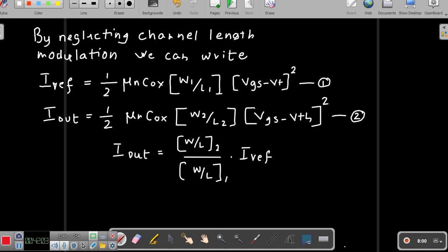Generally it is used to provide the bias current, and it has the features of low input resistance to keep the input current constant. I repeat, low input resistance, right? We have never seen cases of low input resistance. We have got very high input resistance or input impedance, so that the circuit draws a minimum current. But when you have low input resistance, the input current will remain constant regardless of the condition, and high output resistance, right?